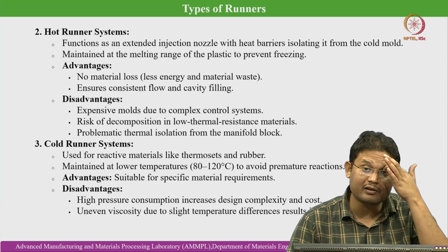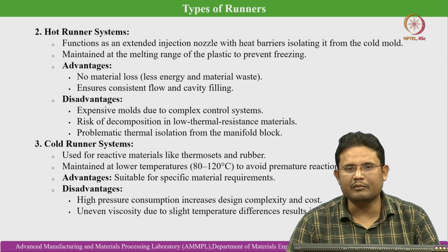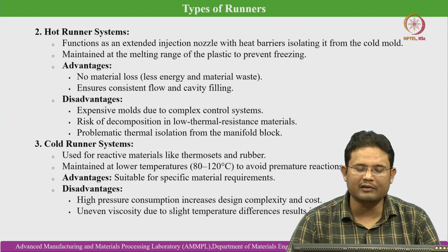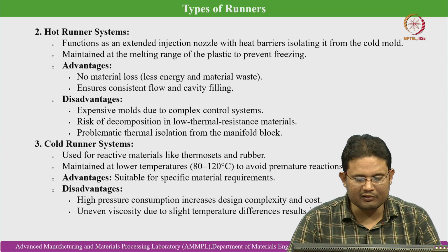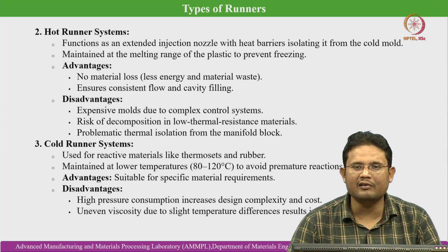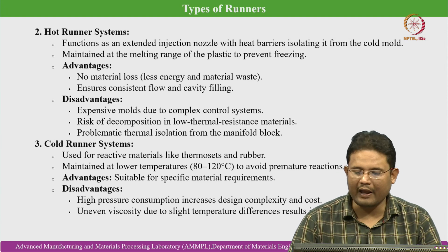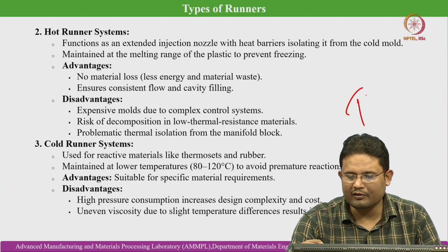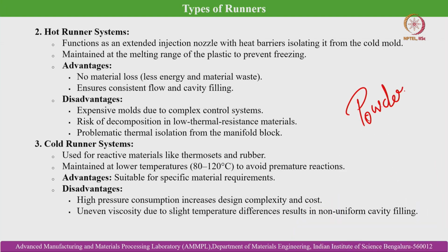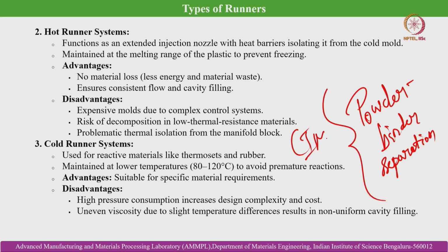However, there are disadvantages for cold runner systems as well, such as high pressure consumption, increased design complexity and cost, and uneven viscosity due to slight temperature differences, which results in non-uniform cavity filling. Another important thing that is not mentioned here is powder binder separation. That is also a key problem, and it is an intrinsic issue for CIM and MIM.